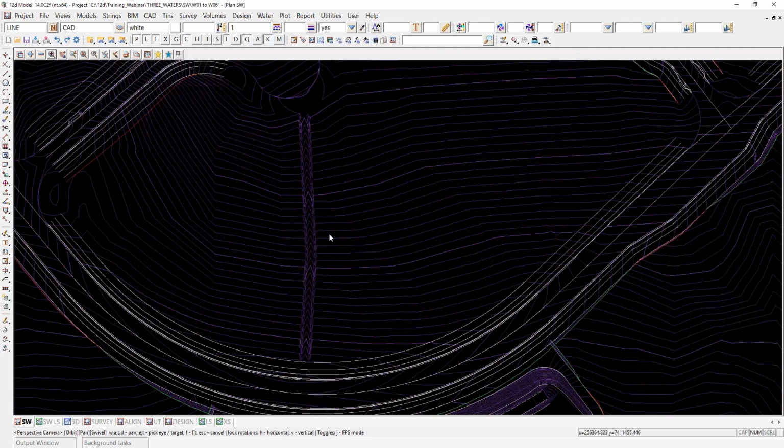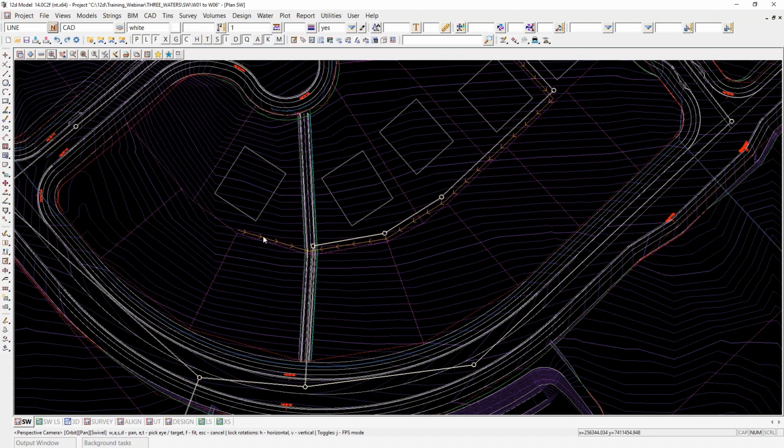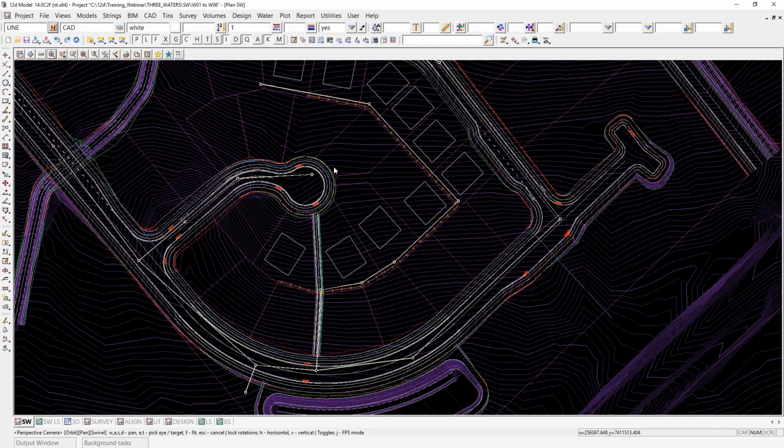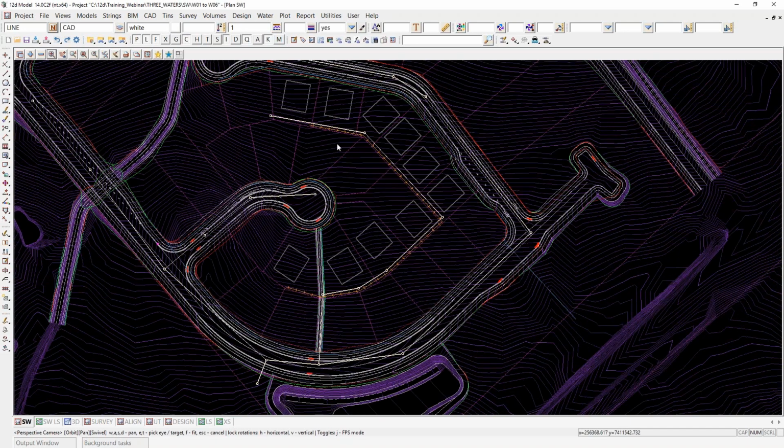In addition, I've got these two orange lines with arrowheads on them. And this is an example of a little bit of preliminary CAD work that might have been done, where you can see these lots with the grey rectangles in them. They've been identified as all the lots that are grading away from the roads they're connected to. And so we're proposing a little bit of rear of allotment drainage or roof drainage just to pick up the runoff from the roofs there.